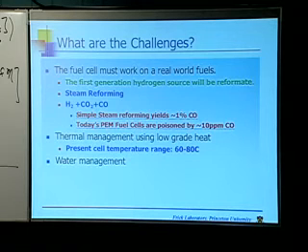And the way we would normally do that in a car is with a radiator, of course, and we do that already with our engines, but our engines are running more in the order of 150 degrees C, and it's really easy to remove 150-degree heat down to room temperature, right? It's not so easy, the so-called low-grade heat, to remove 80-degree heat down to room temperature. And so that means you need a much larger radiator than you currently have. So in fact, the size of the fuel cell isn't an issue, but where you put this radiator is an issue. And if you decide you're going to drive your car in a part of the world where the temperature gets close to 80 degrees C, and there are a few limited places where that happens, then it's not going to work really well. You have no thermal gradient.